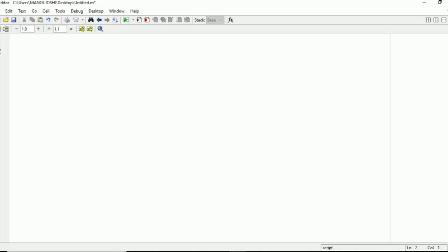Hello to everyone. In this video, I'm going to show you how to find the Z transform of a given signal in MATLAB with and without using a standard function. First of all, you need to write certain commands: clc, clear all, close all. These are basically the commands to clear the command window.